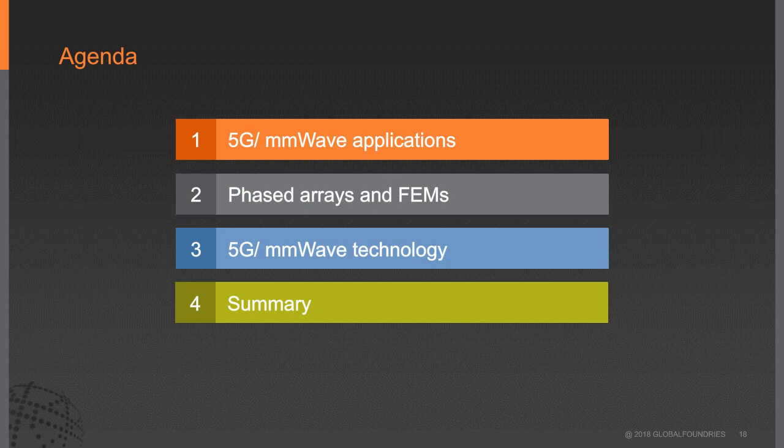I talked about wireless infrastructure, small cells, micro cells, pico cells, and again, the transition from 4G to 5G, where you're going from this huge macro base station with one huge wide beam to these phased array antenna elements, which have very narrow beams, which gives you spatial multiplexing.